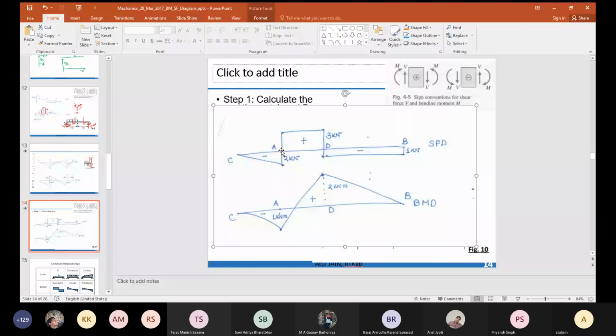In some books, they don't draw this straight line. They draw it as dotted lines, and they say that this location is A minus delta, this is A plus delta, and this is a dotted line. Some textbooks which are very particular about it tend to do this. It's a nice catch. I agree with what you're saying. We cannot define shear force at a point where load is applied. But in reality, you can never apply a point load. It will be a load at a certain distance.